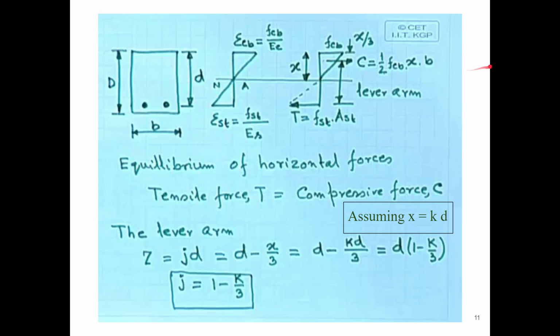So now let us go into the physics and understanding of how we calculate the forces and the capacity. This is the cross section, having a total depth of D, effective depth of small d, width of B, and these are the reinforcement. As I told you, we always calculate up till the effective depth, so this is the extra factor of safety.